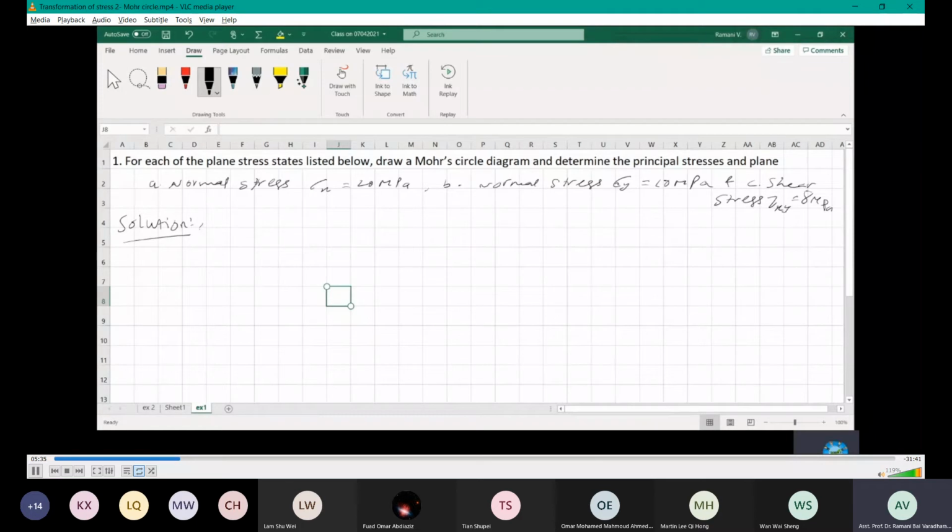Next, the solution. The equations we can take from the formula sheet, which I will provide if asked in the exam, but they are not going to be helpful. That is only a guideline. You need to solve using the Mohr circle to find this answer. The solution starts by drawing the free body diagram of the given plane. Sometimes the plane is given, or you have to draw it like this. The given plane is like this. A box, right? An element at this point.